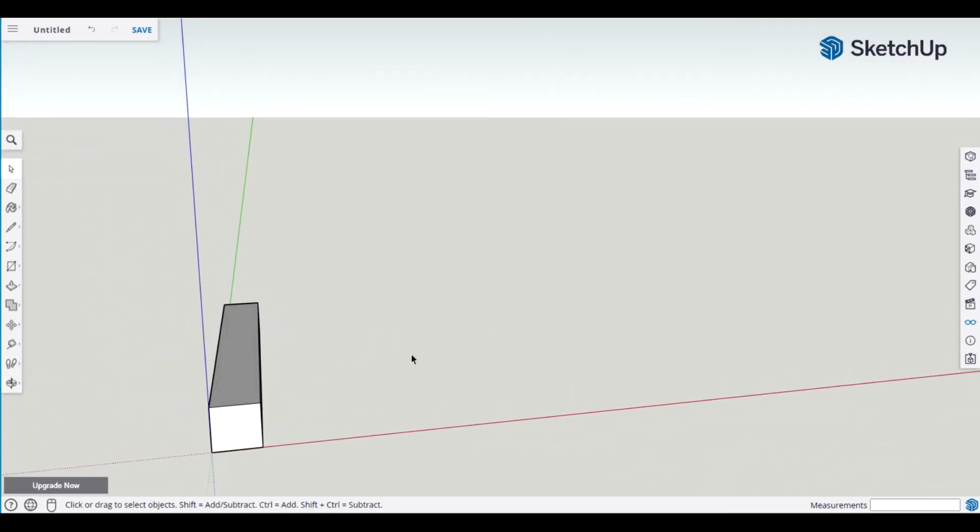Next, we are going to cut a taper, and you can think of this green axis line as your table saw blade. So the taper is going to start 3 inches down and then come in 3/4 inch from the left. So let's first select our tape guide, hit the T, position yourself anywhere on the edge, go down, type in 3, enter, escape key, come in 3/4 inch, 0.75, hit enter, space bar, and now let's draw a line from this point to that point.